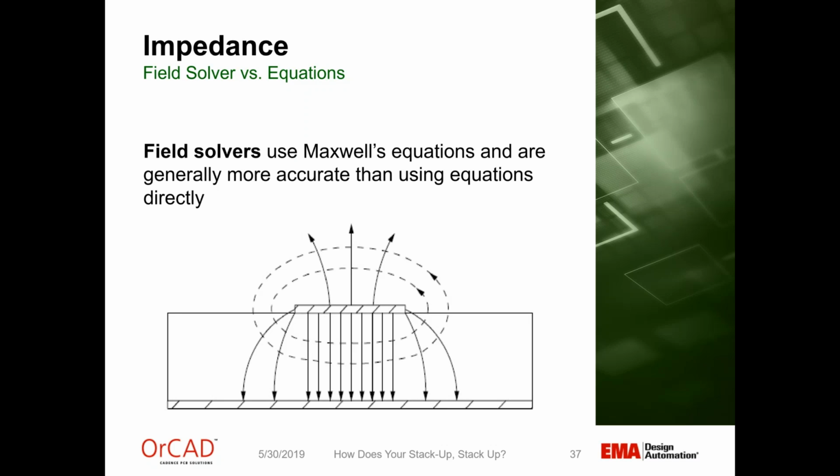Ultimately, though, you need to take this data with a little bit of a grain of salt because you do need to talk to your manufacturer about their process and their techniques, and they'll be able to help you dial it in and get it to a very specific impedance. So if a specific impedance is something that's critical to you, do make sure you're speaking with your manufacturer about how to achieve that.